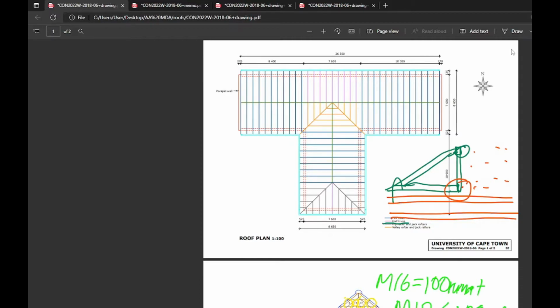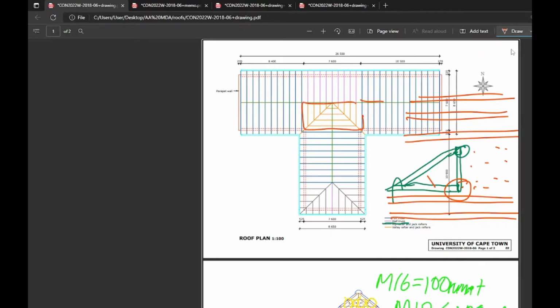and then we'd return back to full trusses down here, right? A bunch of full trusses and full length tie beams, put it that way. This is a half length tie beam. So void over here in your tie beams, there's no void in terms of your jack rafters. These are all your jack rafters.